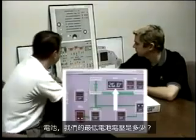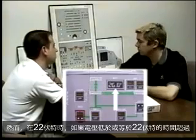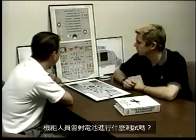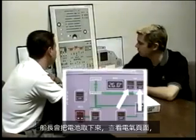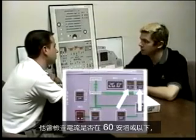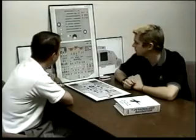Batteries. What is our minimum battery voltage? Min battery voltage 25 volts. However, if it's 22 volts or less for more than a second, the batteries will disconnect. Are there any tests that the crew might perform for the batteries? Yeah, the captain is going to select the batteries off, look on the electrical page, and then select the batteries back on. He's going to check to see that the amperage is 60 amps or less, and it's decreasing within 10 seconds. What about fault in the battery switch? It's just an abnormal charging rate.